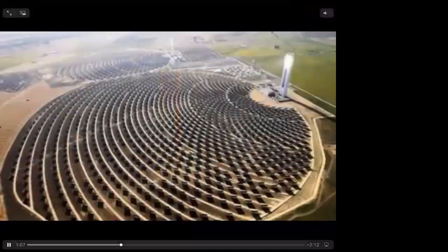I want to point out one very important thing. This arrangement of the heliostats, some of you might say, is reminiscent of sunflowers. And that's exactly true, because it's a fractal arrangement which depends on the latitude of the location. It gives you the most efficient coverage, because you want to minimize shading between the heliostats while maximizing the aerial coverage. That turns out to be this fractal arrangement, which of course evolution has done for sunflowers.